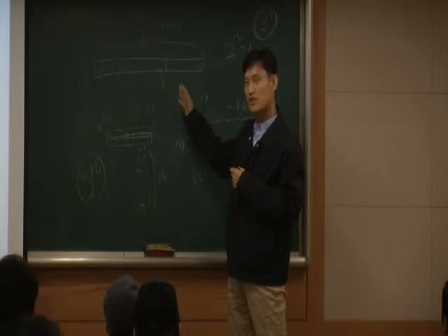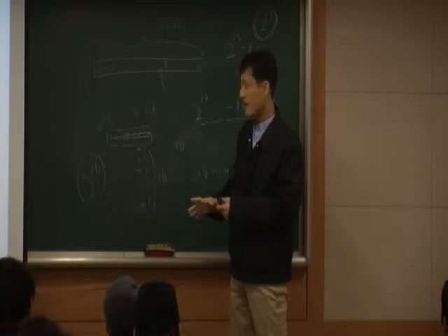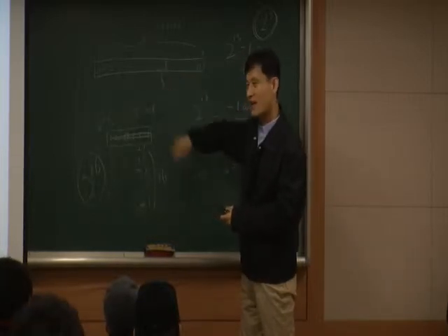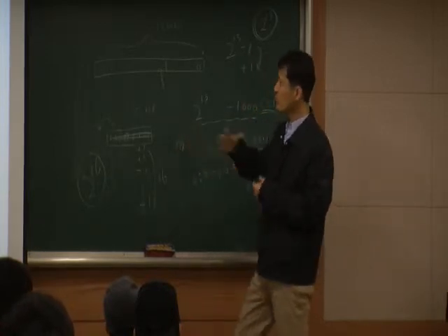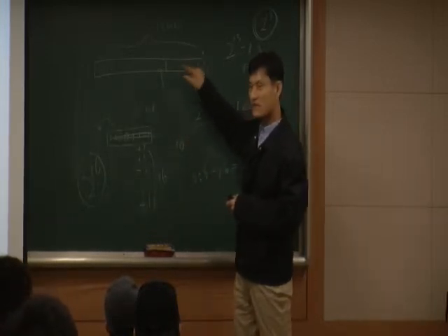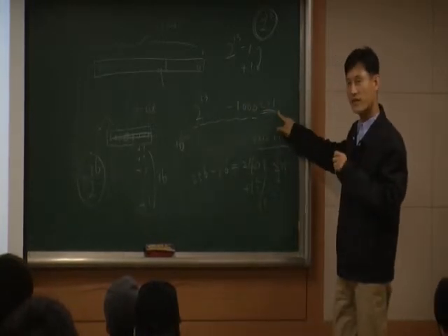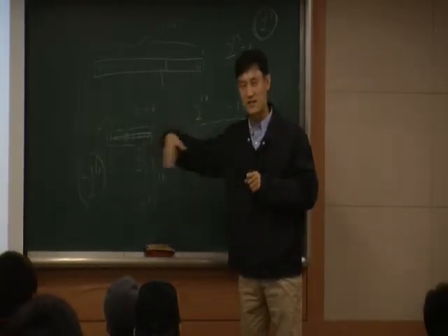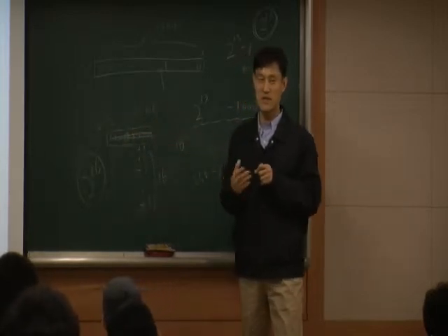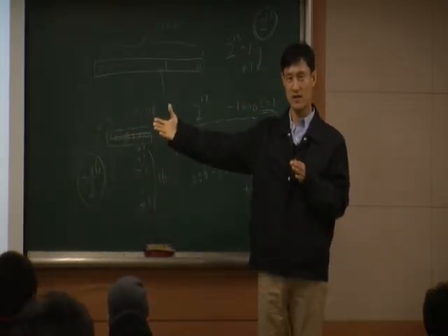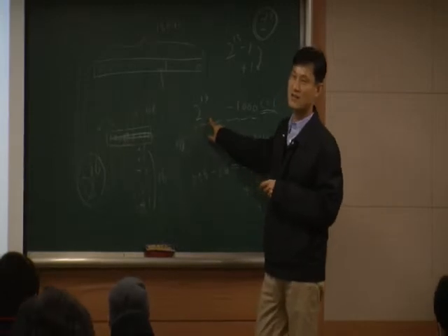So what do you need to do? You need to stop the timer and program this value again and run it. So you have to keep writing this value, the initial value. Whenever the carry happens, whenever the carry is on, then you need to reinitialize it. Only then it becomes a 1 millisecond delay. Every time you need to initialize it.